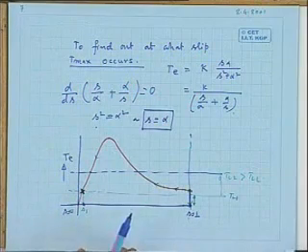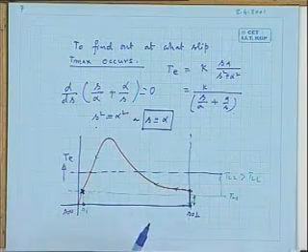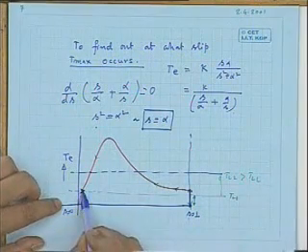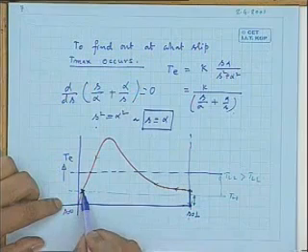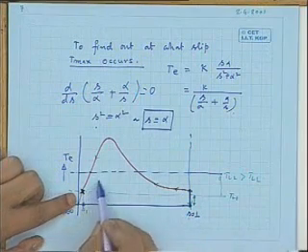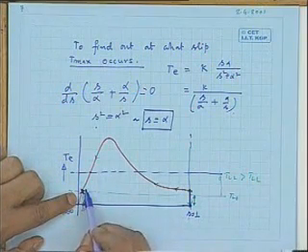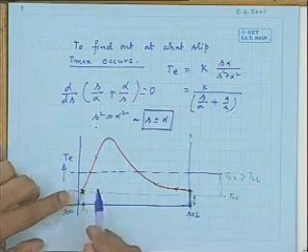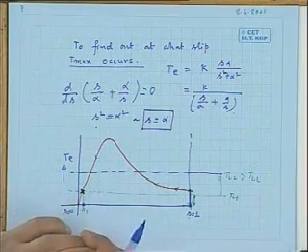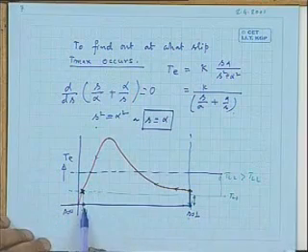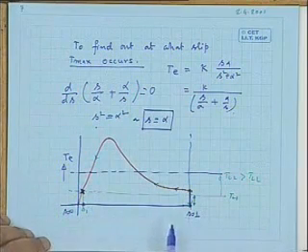It is still this much. Speed has not changed. The moment you have increased the load torque from TL1 to TL2, the electromagnetic torque developed by the machine is this much, but the load torque is higher than the electromagnetic torque. So what will happen? The machine will decelerate.